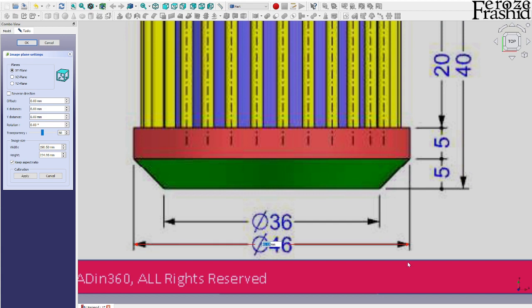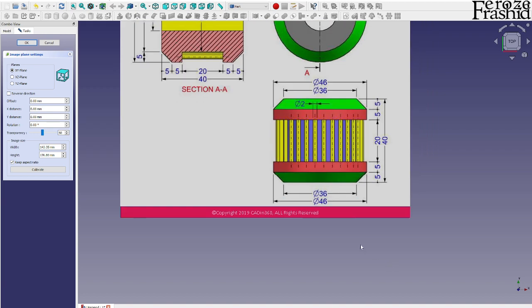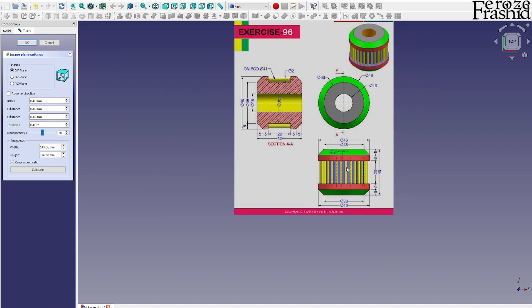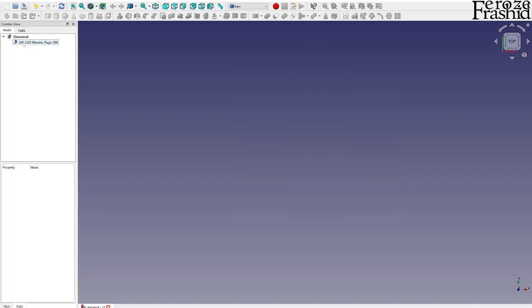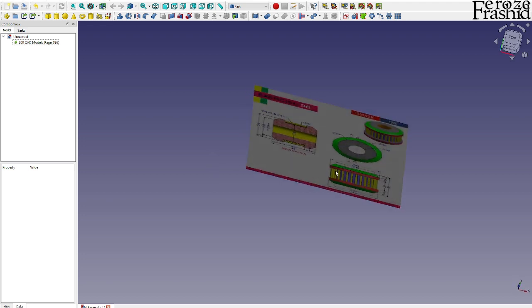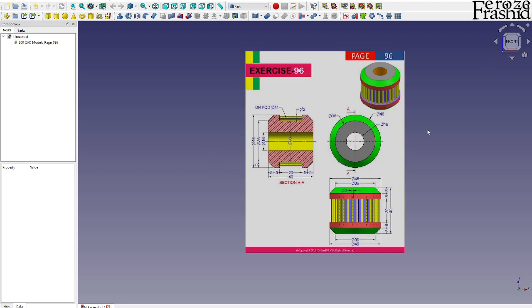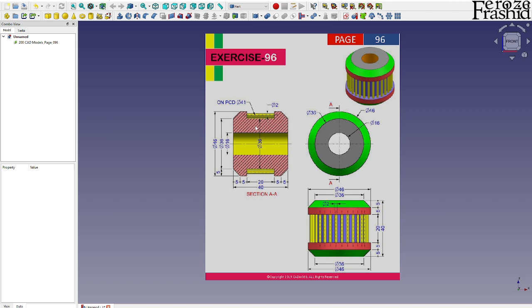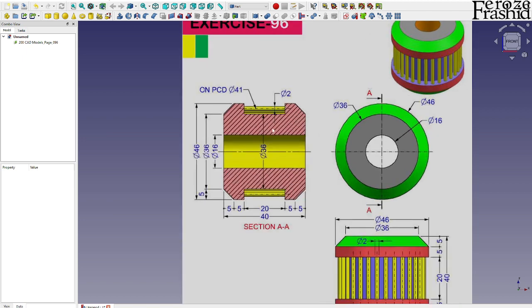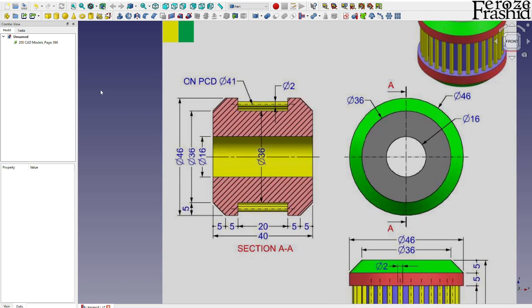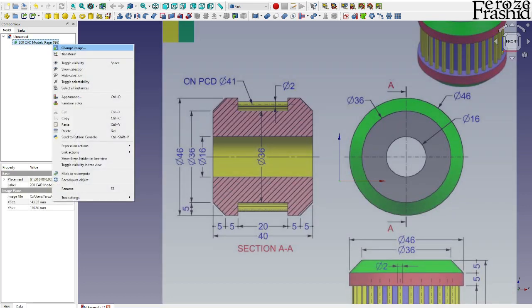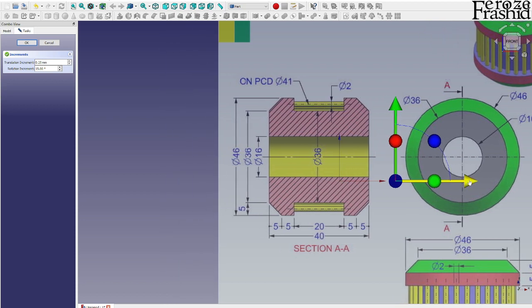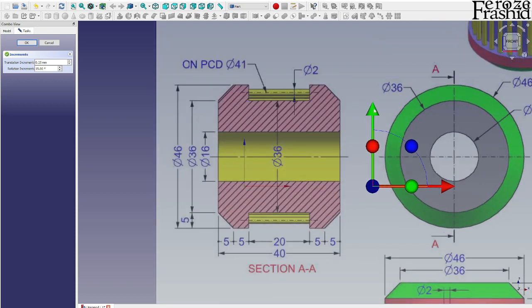Nevertheless, we'll have to do the image processing to help us with sketching. And I want to start sketching on XY plane, on XZ plane, I'm sorry. So let's go ahead and place it on XZ plane, which is on the front side. That's what I want to sketch, right? So let's go ahead and relocate the image so it makes some sense in sketching.